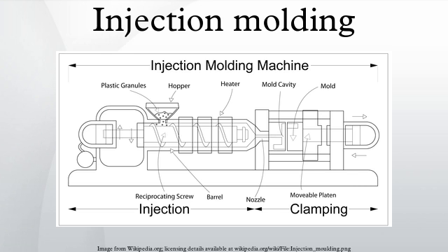Major criteria for selection of a material are the strength and function required for the final part, as well as the cost, but also each material has different parameters for molding that must be taken into account. Common polymers like epoxy and phenolic are examples of thermosetting plastics, while nylon, polyethylene, and polystyrene are thermoplastic. Until comparatively recently, plastic springs were not possible, but advances in polymer properties make them quite practical. Among such applications are buckles for anchoring and disconnecting outdoor equipment webbing.